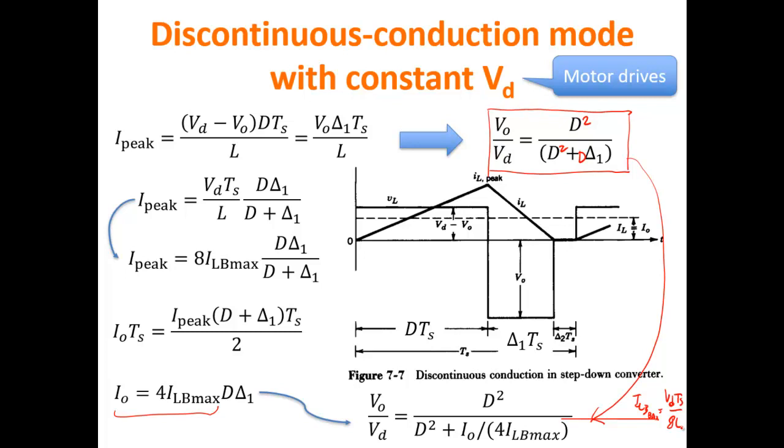This is very critical from the point of view of the system, because if you think in terms of the power supply of a transmitter. A transmitter typically transmits in packets, in low power radios such as low power Bluetooth, for example. You switch on the transmitter, you transmit a packet, and then you switch off the transmitter. So in the time of a few milliseconds, the power absorbed goes up when you transmit, and then goes rapidly down.